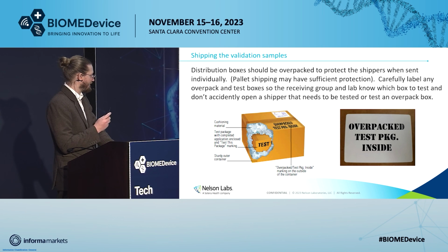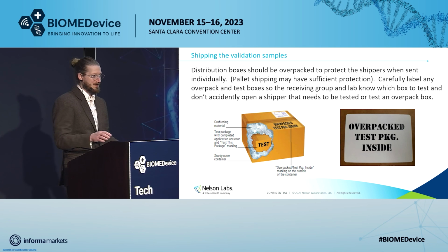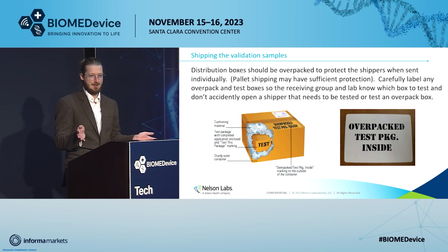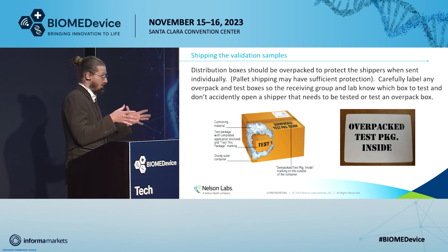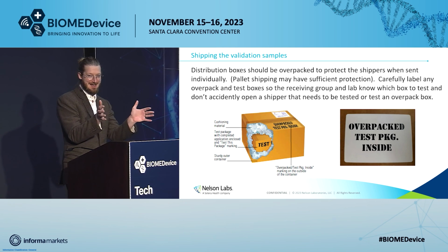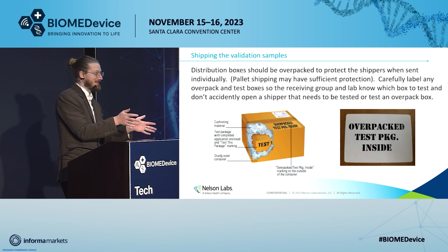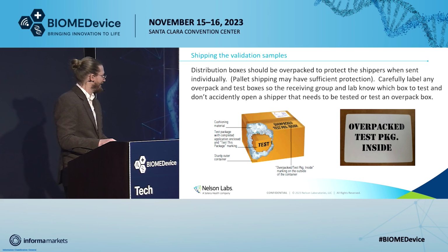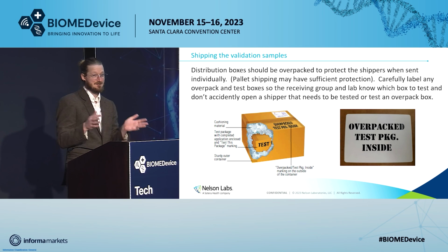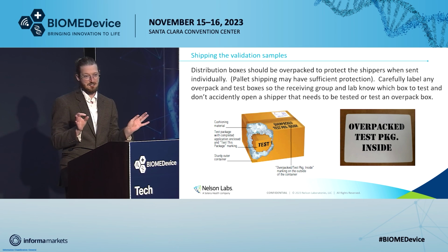And this is kind of another big one that I want to emphasize a lot. When you send something to be distribution tested, it kind of already goes under a distribution test, right? On its way to the lab that's doing the testing. So you want to protect your shipper box as much as you can, meaning overpack it. So whatever your shipping container is, take that, put that box in a box, as Yzma from Emperor's New Groove might say, right? And protect it as much as you can so that when it actually gets tested, it's in as pristine condition as it can be.